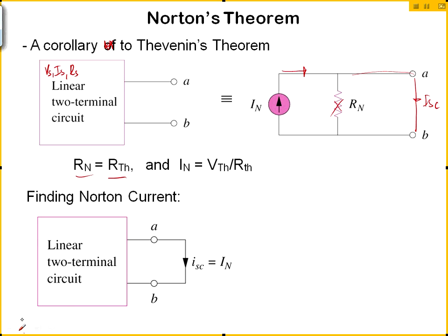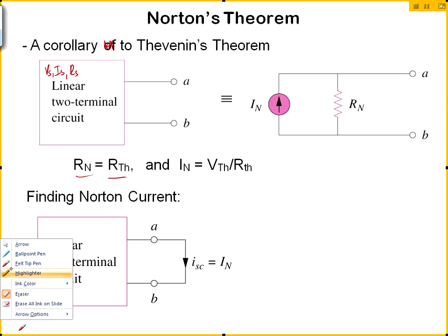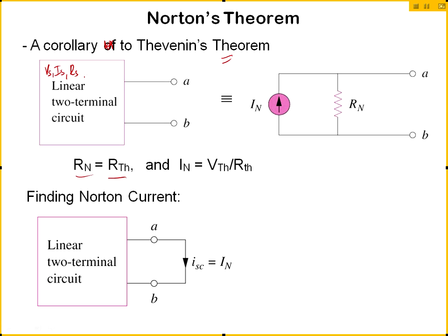So what I was saying is it was kind of cheap because if you recognize this, it's really just a combination of Thevenin plus source transformation. Because according to Thevenin, what does Thevenin say? According to Mr. Thevenin, the left side is equivalent to a V Thevenin in series with an R Thevenin as seen by the terminals AB. And we also know that source transformation allows us to transform that voltage source in series with a resistor into a current source in parallel with the same resistor. It's kind of cheap, you know. It's like he puts the Thevenin and source transformation together, and now you have it.